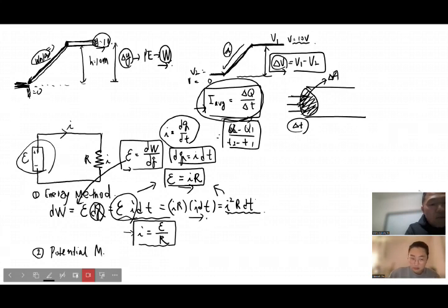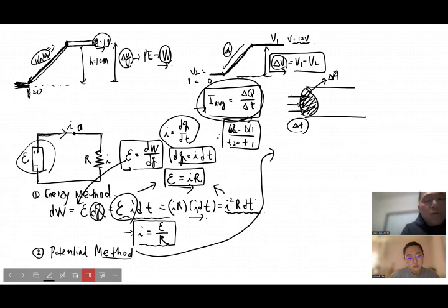I'm just giving you a basic method to analyze the simplistic circuit model. So the potential method is now, if you pick one point out of this closed loop and go along this closed loop, the resistor normally produces a potential drop. So when current goes through this resistor, the potential is just lower. And once this current comes back to this battery, it increases the potential, as long as you're going along the positive direction from the negative bias to the positive bias. So if the closed loop direction is the same as the current flow, you gain energy, but the resistor lowers the potential.